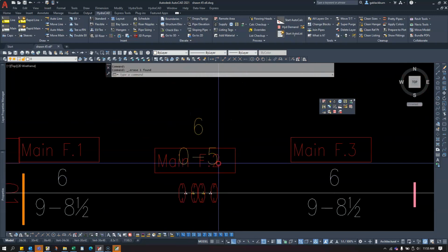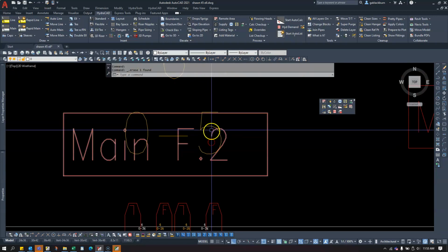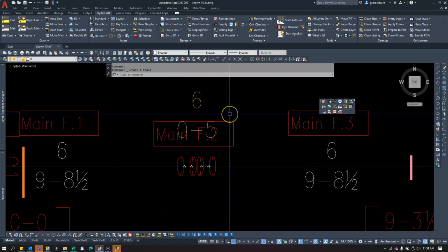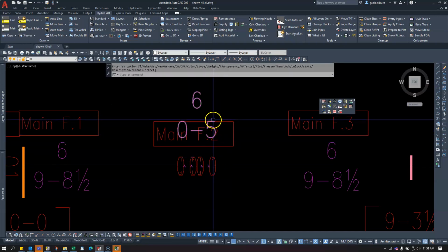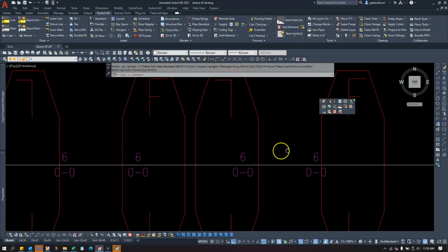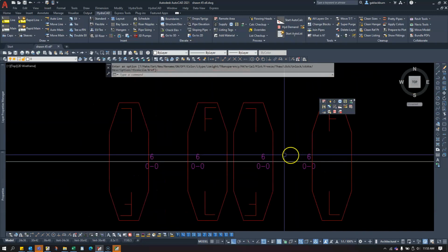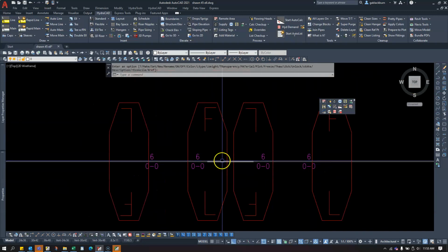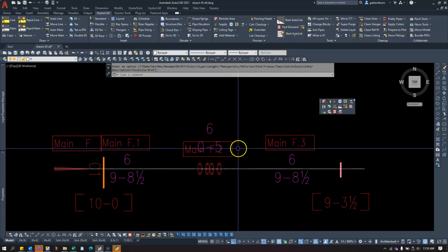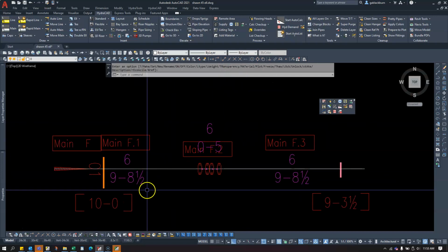Now, the other thing I'm noticing here is my center to center length is 5 inches for my spool piece. I'm going to type in CUL to see what my cut length is, and we're hoping for the same. It is. It's the same. It's 5 inches, so that's a good sign. And all of these takeouts for our grooved elbow are 0, so that's a good sign as well. So I want to say this worked. Even though we got those 2 warnings, I want to say this worked.